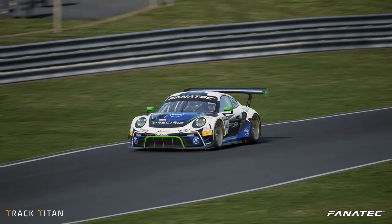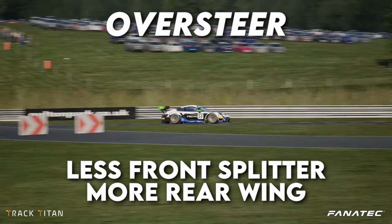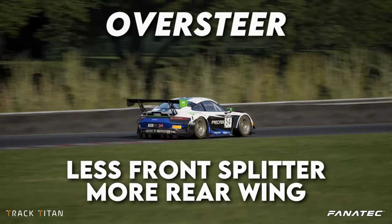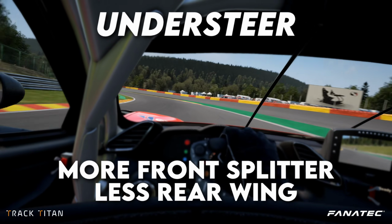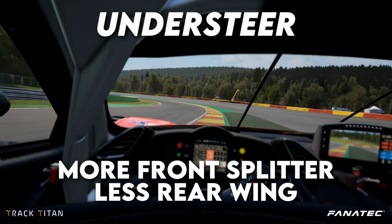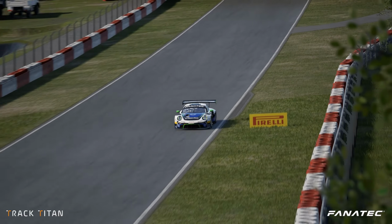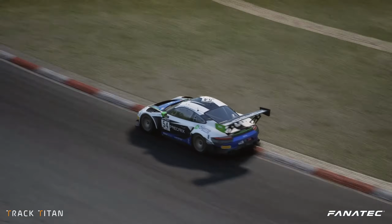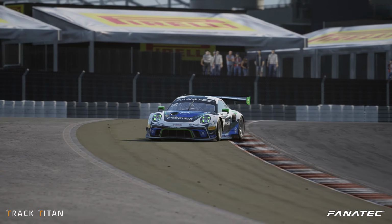If you're feeling oversteer in those high speed corners, use a little less front splitter or some more rear wing. It's of course the other way around if you experience understeer in those corners, as you'll want more front splitter and less rear wing. Try to minimize your rear wing without losing grip to make yourself just that little bit faster on the straights, but don't make your car unstable.